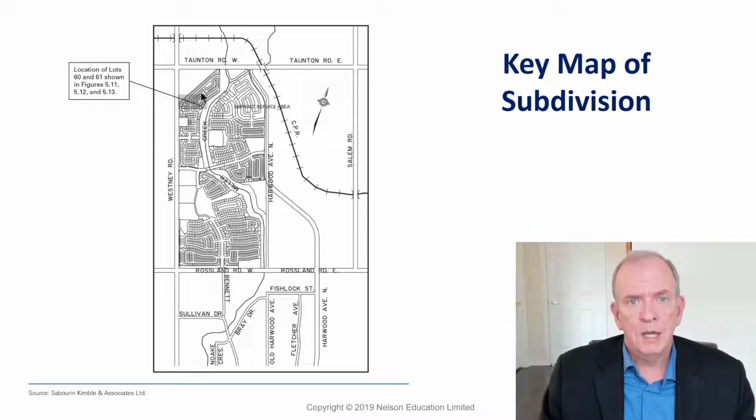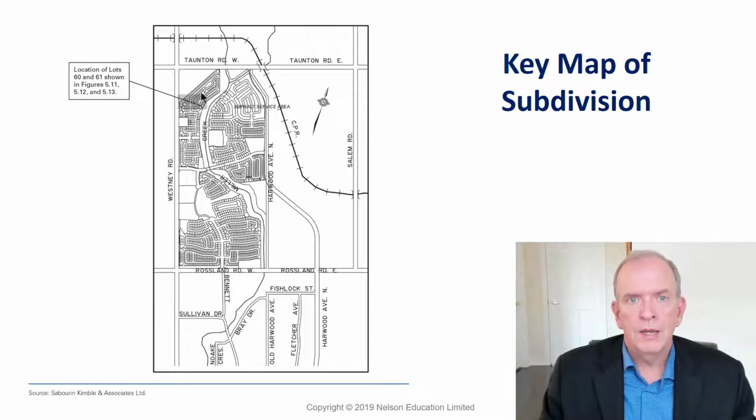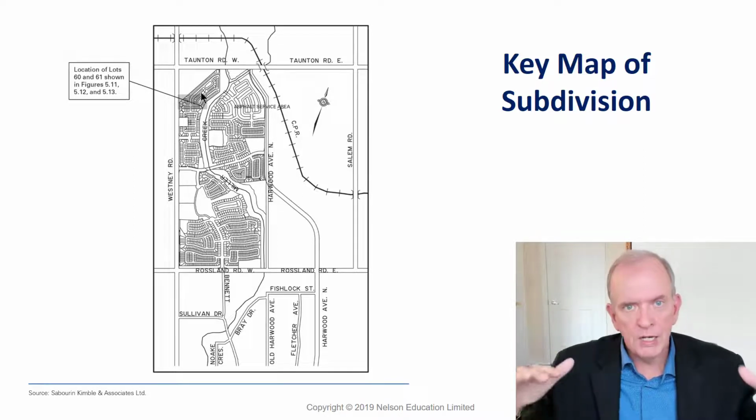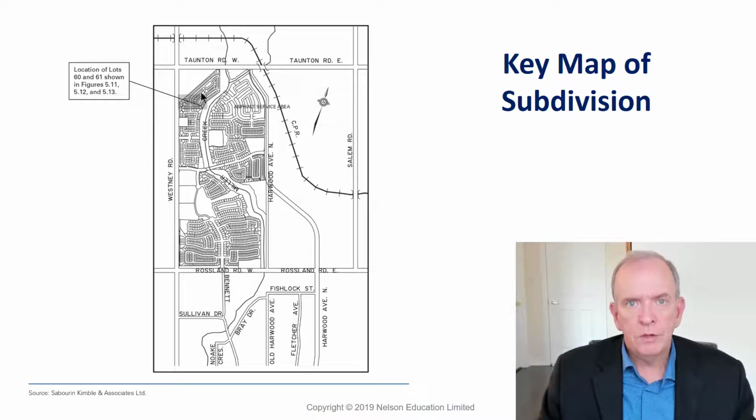but the existing topography and how to take advantage of the existing slopes and natural curvature of the Earth's surface and regrade it and adjust it so that within the streetscape and the layout of the roads there's the capacity that the water will run away from the houses. You don't want it running to the houses, so you always want it to slope away from the houses where possible,